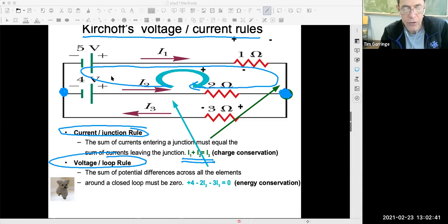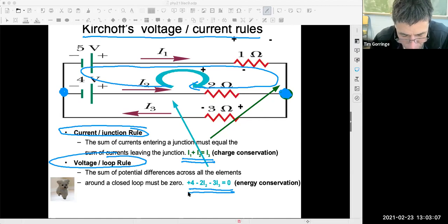After you've gone all the way around the circuit, completed your loop of the circuit, those ups and downs, if you add them all up, the net up or net down is zero. Ultimately, when you get back to where you started, the potential changes all add up to zero. And so that's the loop rule. And I've tried to illustrate it here for this loop with this equation.